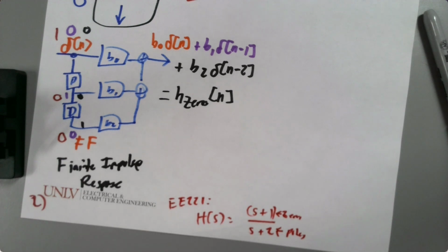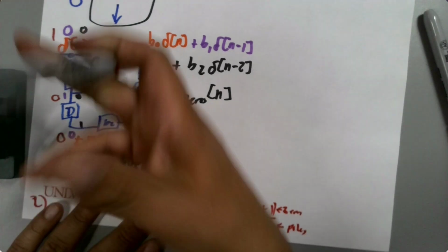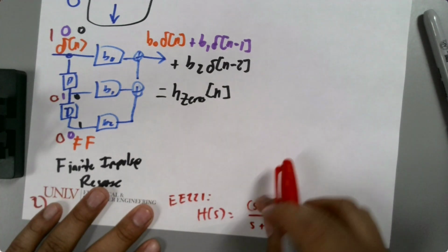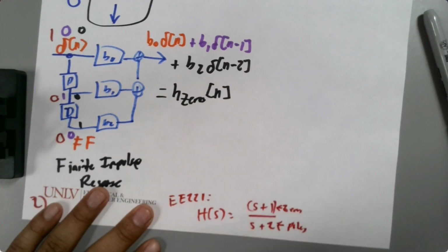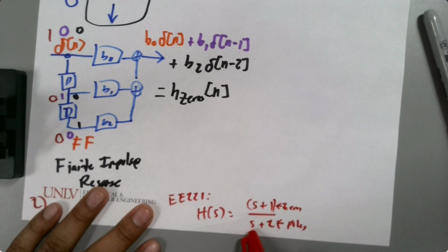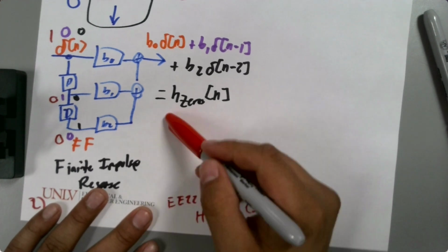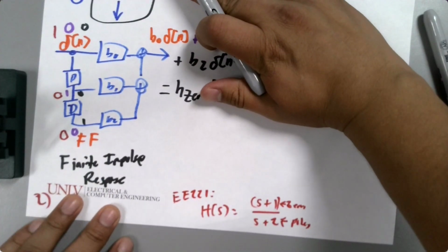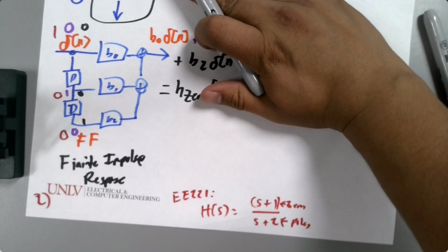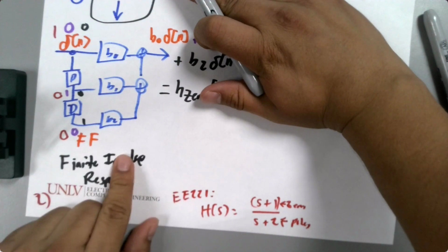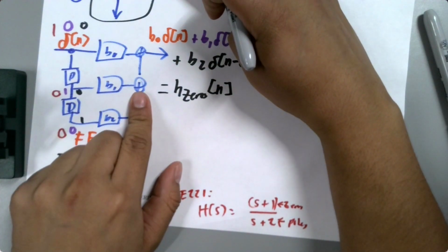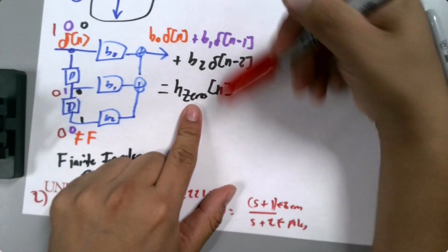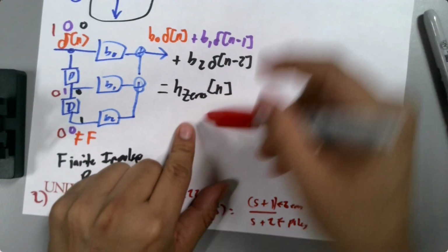So that's the reason why we call them zeros. Well, they don't blow up. You throw something in here, and if you put a 0 or any number into s, it doesn't blow up. But we see right here, if you put this s to a minus 2, oh, it goes to infinity, the entire thing. So before I get into that, you understand that if I were to tell you to design me a feed forward path, just a feed forward response, what is the impulse of this feed forward block? Got it? All right, and that's our H0 of s.